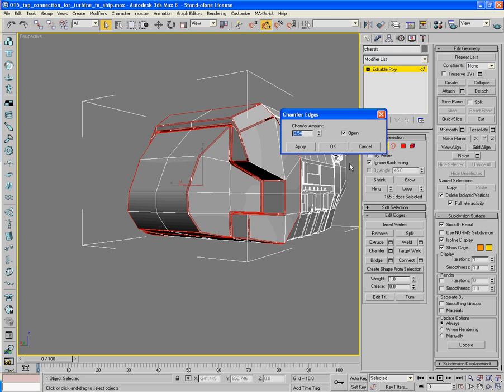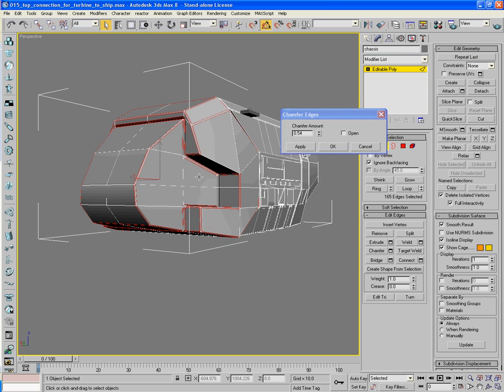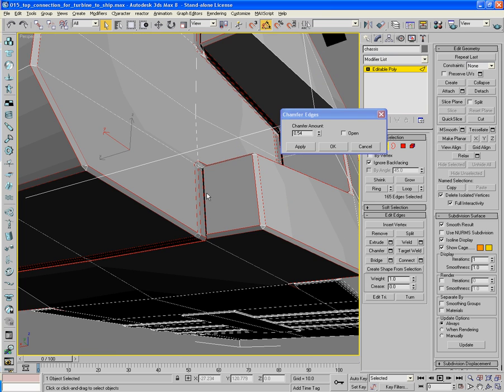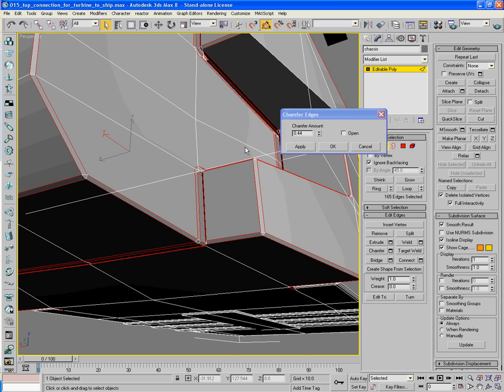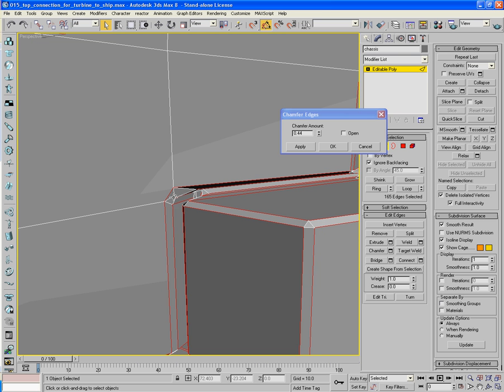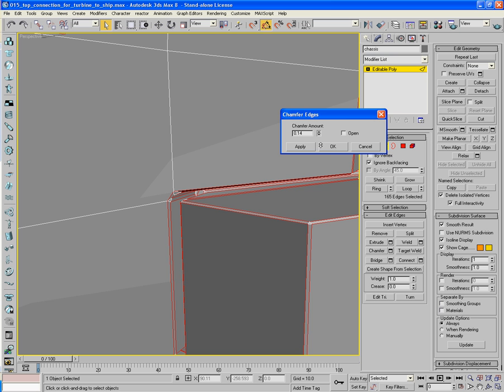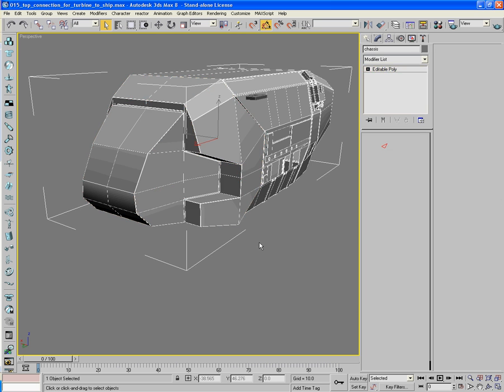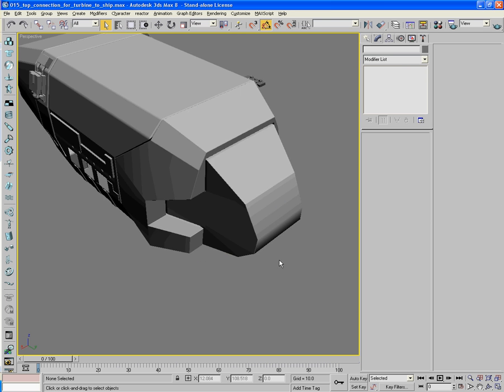So if we turn on chamfer, don't open it this time. Check all our areas. And we're looking for pieces like this, you see. We know the chamfer's too big because it's intersecting too much. So we're just going to use a smaller chamfer there. Click OK. There.